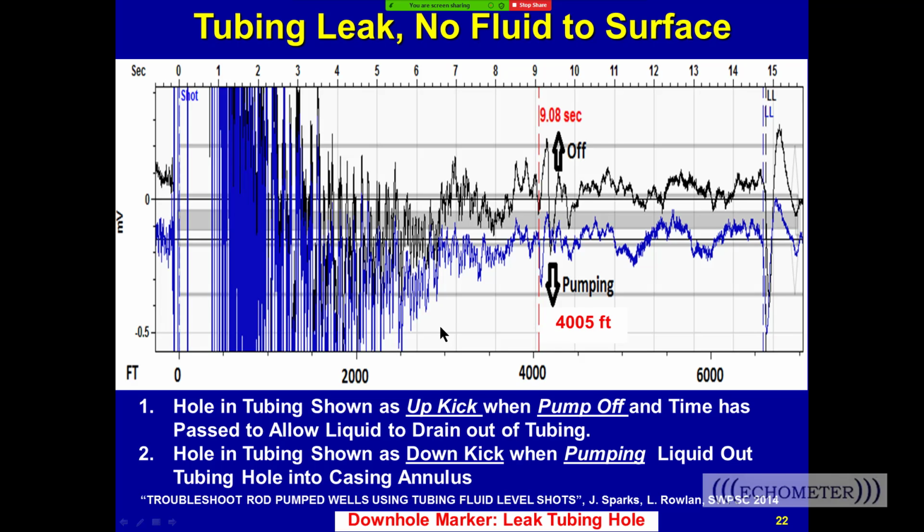This is a rod pump well up in Oklahoma, and the operator that collected this data called and said, "Hey, I've got this pump car that's full of liquid, but no liquid's coming out the tubing." And we talked about it and said, "Well, when you shoot the fluid level, do you see a down kick when the pump's running?" And he said, "Yeah, there's a little down kick above liquid level."